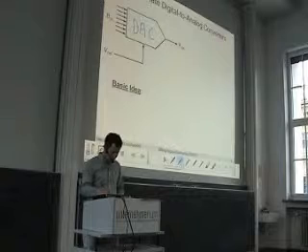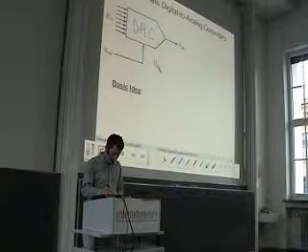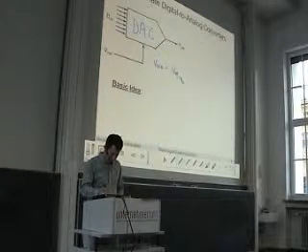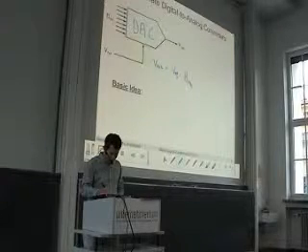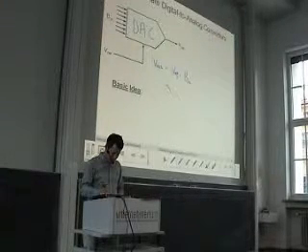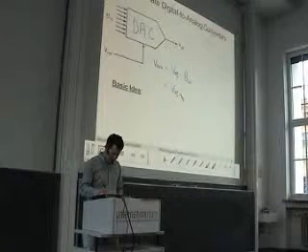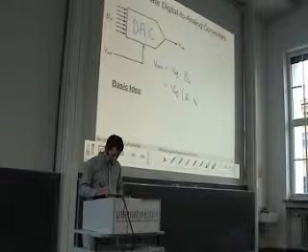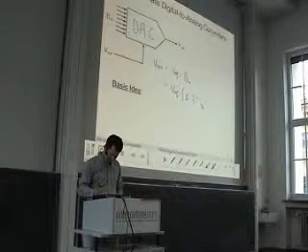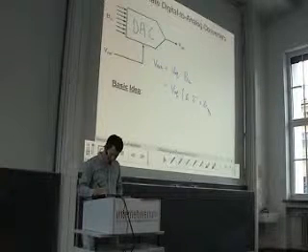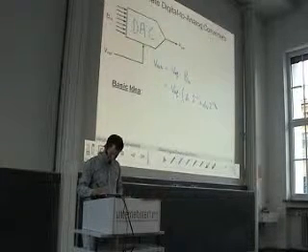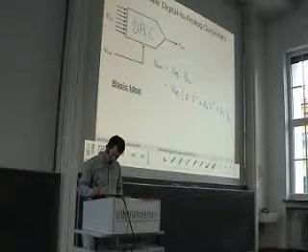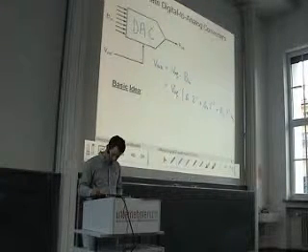So what we want to achieve is a V out equal to Vref times the binary input word B in. And you remember this was defined as Vref times B1 2 to the power of minus 1 plus B2 2 to the power of minus 2, and so on, and so on. So B3 2 to the power of minus 3 plus ...